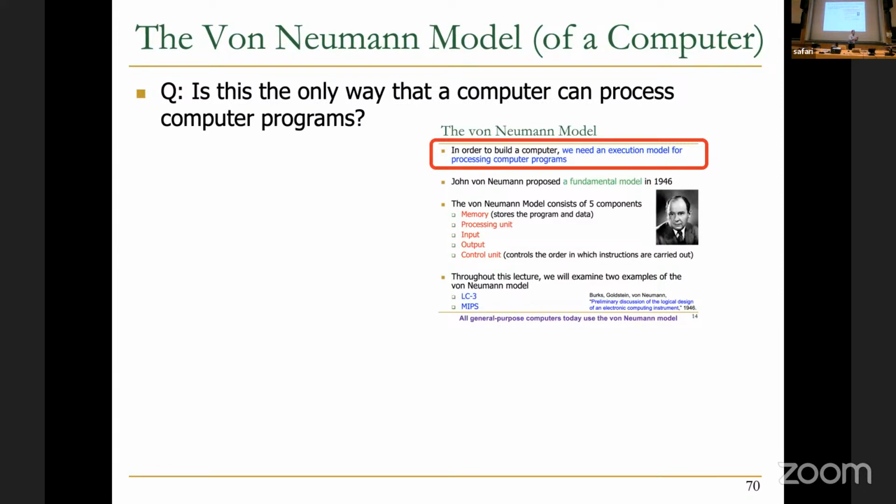That's true. I mean, those break the von Neumann model, but I was also thinking of more general purpose paradigm, right? Once you go entirely specialized, of course, you don't even need to have programs, right? Almost. But very good. I mean, these specialized chips like hard-coded application-specific integrated circuits that just do video decoding, for example, they don't really obey the von Neumann model, right? Systolic arrays that are at the core of a lot of machine learning accelerators, as we will see, they don't obey the von Neumann model. So we will see examples of it.